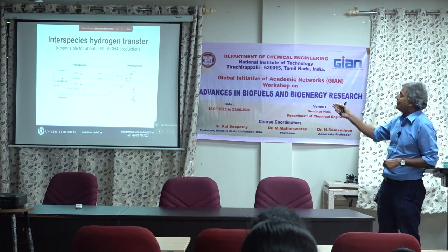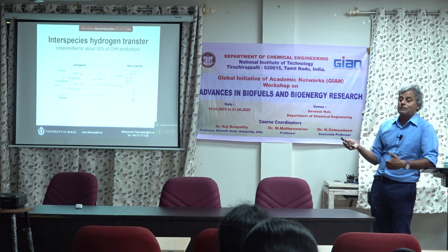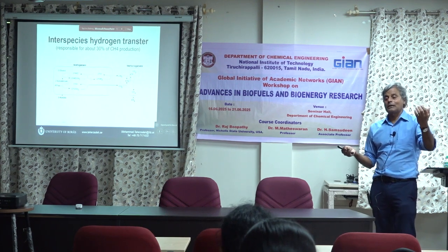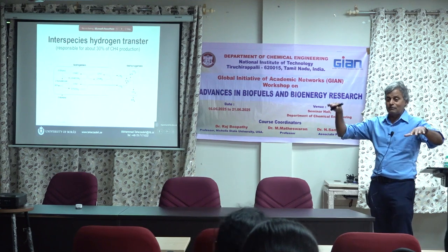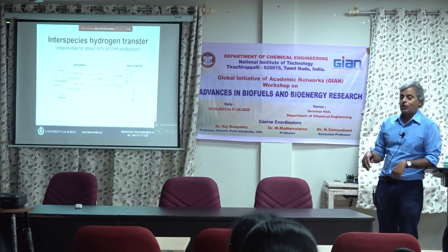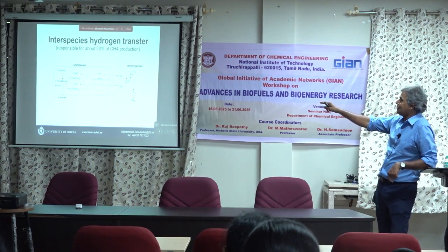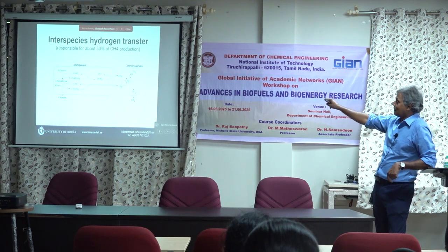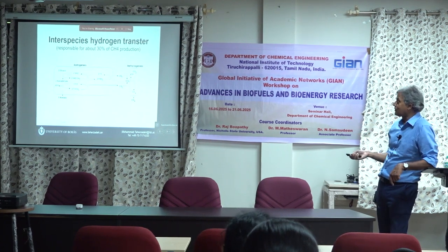That's what's showing here. The hydrogen is transferred from one bacterial species to another bacterial species. When bacteria produce too much hydrogen, the hydrogen consuming bacteria are going to utilize this hydrogen. So you have this harmony of hydrogen in your digester, so you don't upset the whole system. Okay, so we have hydrogen produced during acetogenesis. The methanogenesis bacteria, the methane producing bacteria, take the hydrogen and transfer the hydrogen between these two groups, and that is called the interspecies hydrogen transfer process.